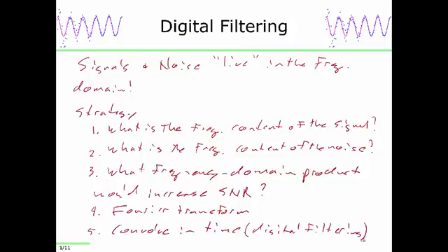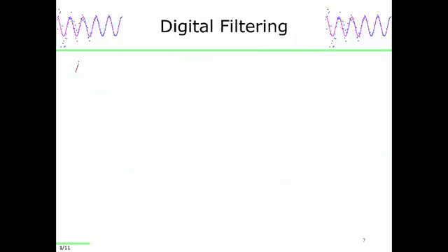Let's say I have my rolling average, and I wanted to remove the DC, remove the zero frequency content in a rolling average. What's that going to look like? Example. I'll call it a running average, because that's what the lecture notes call it. A running average modified.